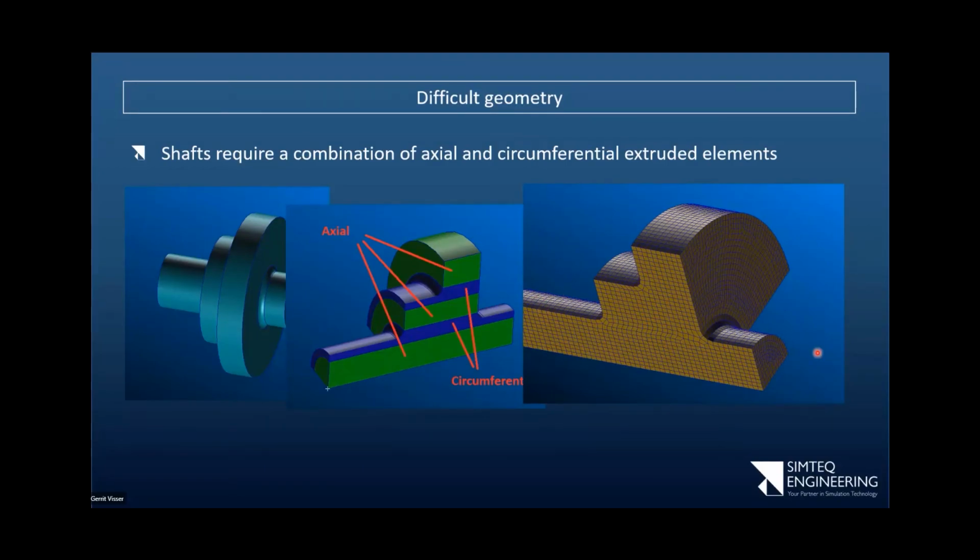I'm just looking at it from that side now, and there you can see it's quad elements all the way. There may be one or two trias, but they'll be almost non-existent. We've got nearly perfect elements on the inside. We've got really good elements there. All of these regions on this side are not necessarily perfect. I could have improved the mesh there, I agree, but it's still pretty decent.